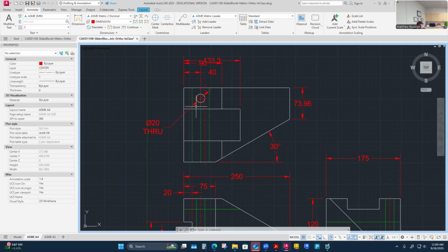So when we really look at inspecting and controlling parts, I try to minimize how many datums I'm using, because datums become these really hard controlled surfaces: their flatness, how smooth they are. I can establish all kinds of real specific control on datums. So I don't want to make extra part labor to make every surface on a part a datum that I'm pulling dimensions from. I try to actually look in the future and say there are better things to pull from.